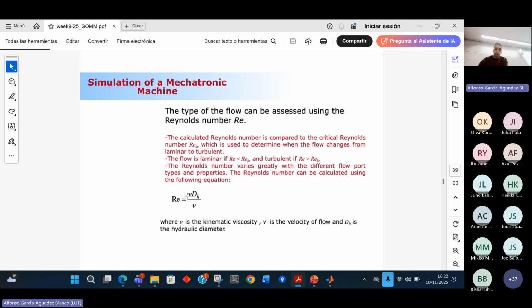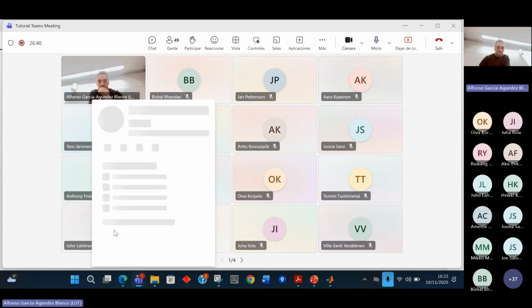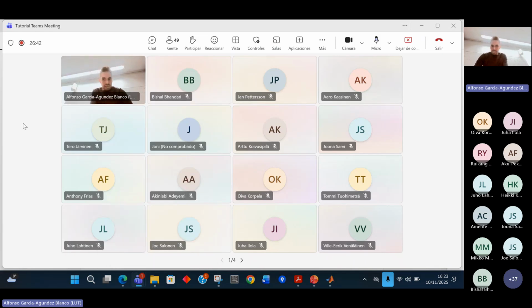So, as mentioned, in the numerator, mean velocity of the flow times the hydraulic diameter. In the case, for example, of a circular pipe, you would have here the diameter of the circle over the kinematic viscosity, okay? Is the definition of the Reynolds number and the transition between these flows clear? For the students online, please interrupt me, react, or ask whatever you need, okay? Clear so far?